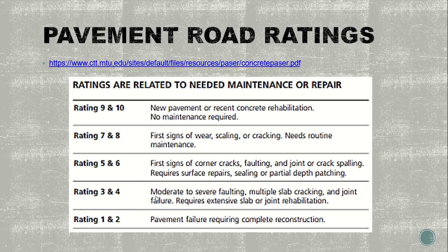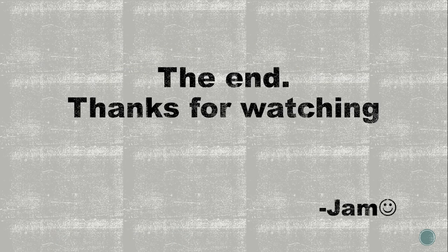For ratings 3 and 4, moderate to severe faulting, multiple slab cracking, and joint failure, this requires extensive slab or joint rehabilitation. And for ratings 1 and 2, this is where pavement failure requires complete reconstruction. So basically, that's all that you need to learn about concrete roads.